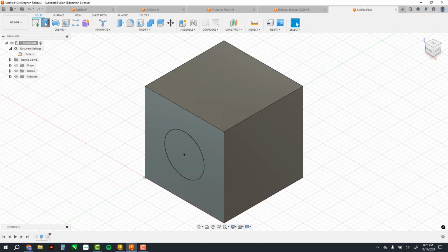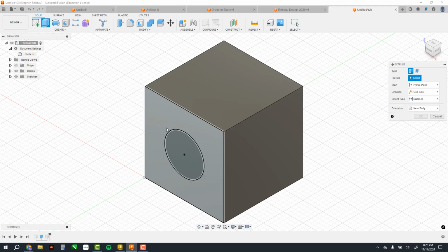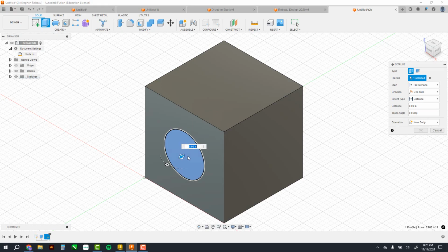We're going to click extrude again. But now there's 2 different options. We could do something to this or this. There's 2 different profiles. We want the inside one, so we left click on it, and then we just move this out. I like to just barely move it out just so I know if I'm going plus or minus direction. So I'm going plus because there's no minus. Look, you can go in and it would show minus. So I'm going plus. I'm just going to do 0.5.